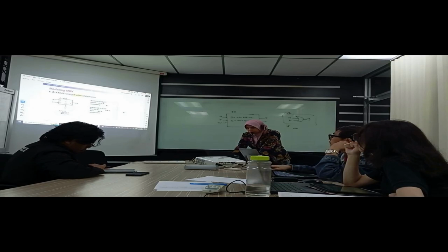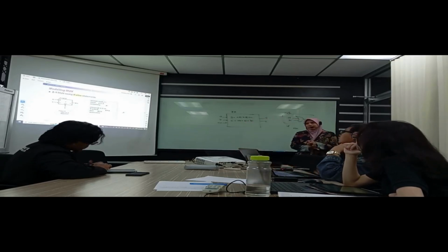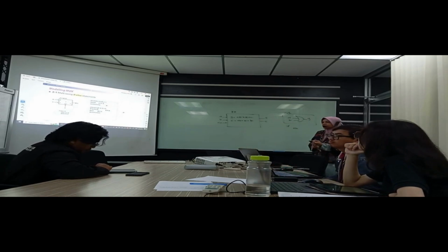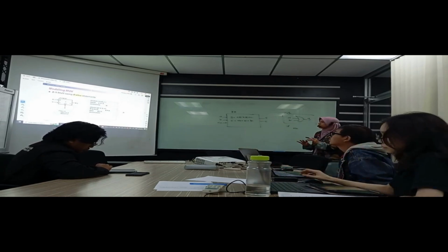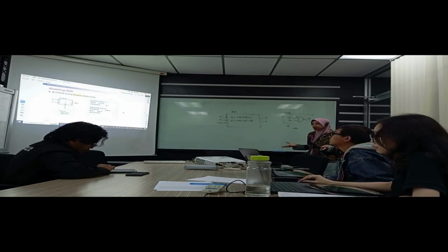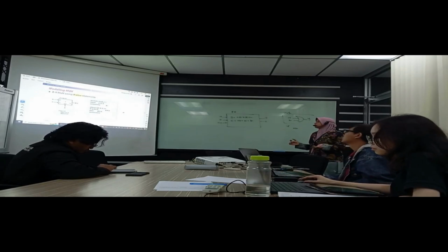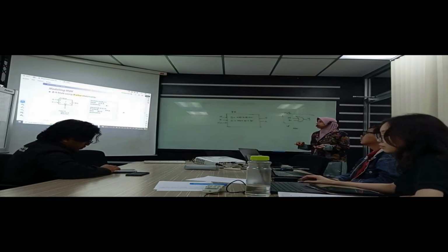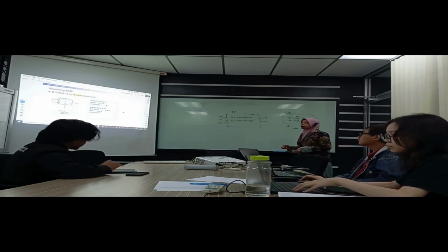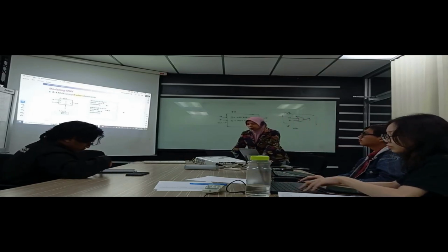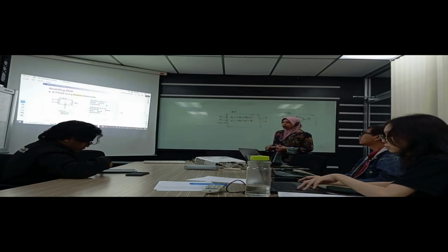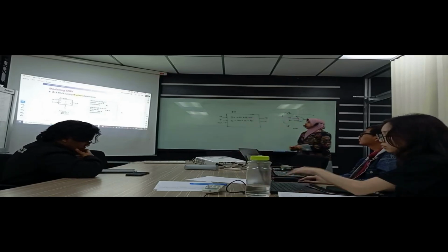Since you know that for the combinational, you can use 3 modeling, instead of only one like the sequential. So now we want to design, let's say, a multiplexer. Instead of using the data flow modeling only, then we use the if else, because if else is much easier than this.